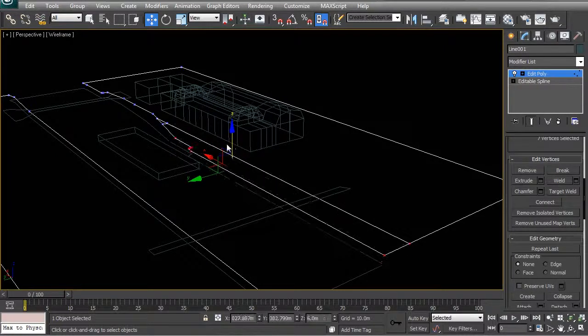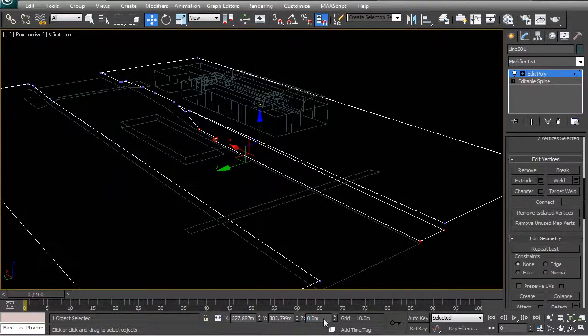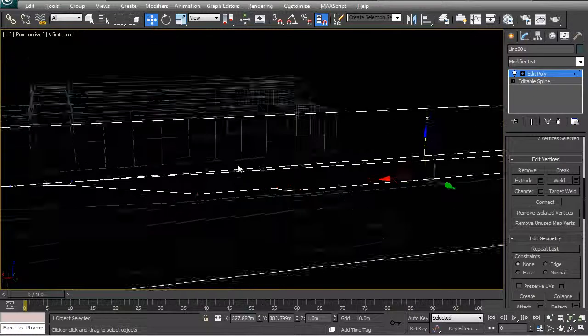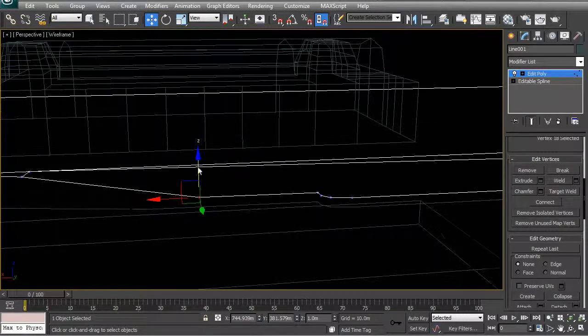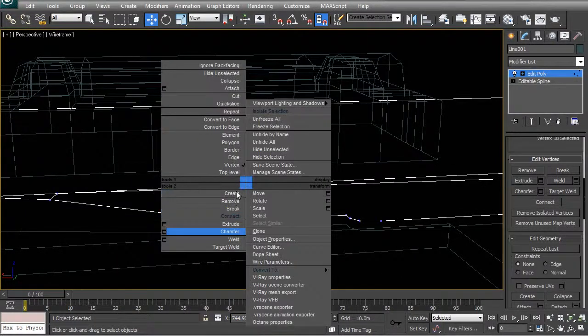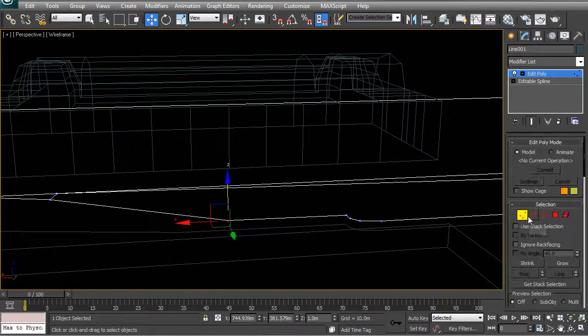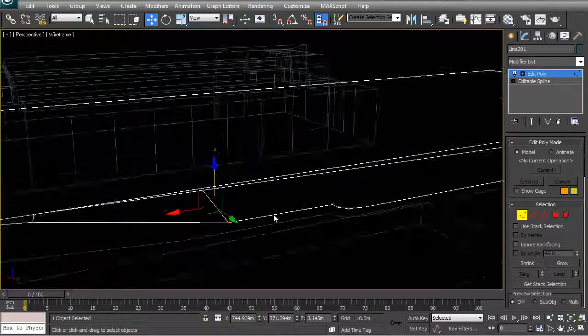So what we can do here is that we can move it all to 0, and let's just make it 1 meter above the water. Next, it would be a good idea to add another vertex more or less in that position. So if I look at the x coordinates, I'm just going to copy that, and I'm going to add another vertex round about there, and I'm going to paste that figure, right click and connect these two.